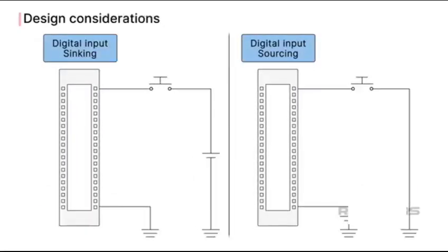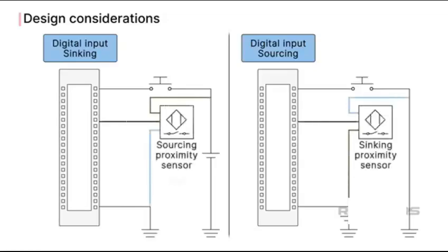What does the instrument you are wiring to require? Instruments may have PNP or NPN transistors in their circuits. P stands for positive, and N stands for negative. Positive and negative refer to the current polarity. This will determine what power sourcing needs to happen. Transistors, as opposed to relays, rely on polarity. Many proximity switches have PNP or NPN transistors today.